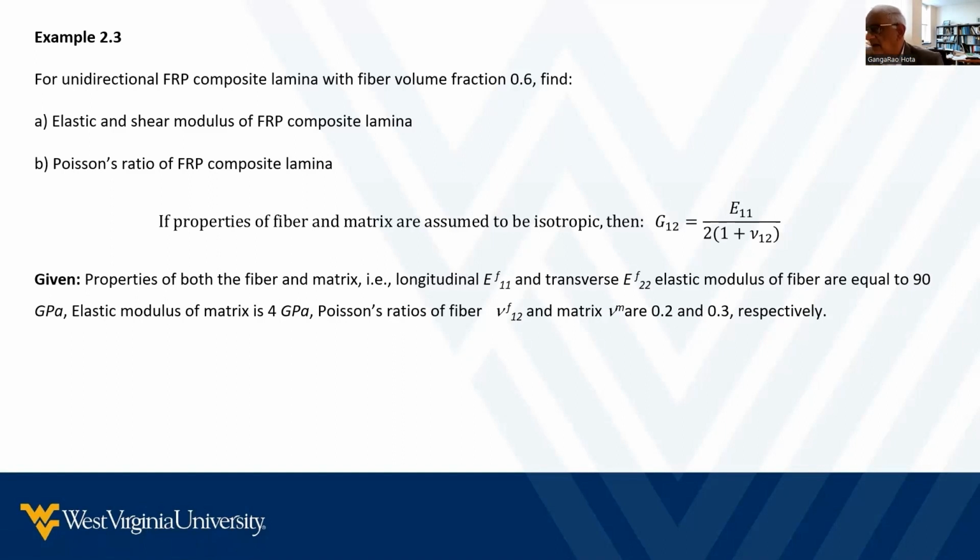That implies about 2.4 times lower modulus for the glass fiber than steel. Please note, this is the S glass fiber, not the E glass fiber. Typically, the E glass fibers have a modulus of about 10.5, 10.6 million PSI.